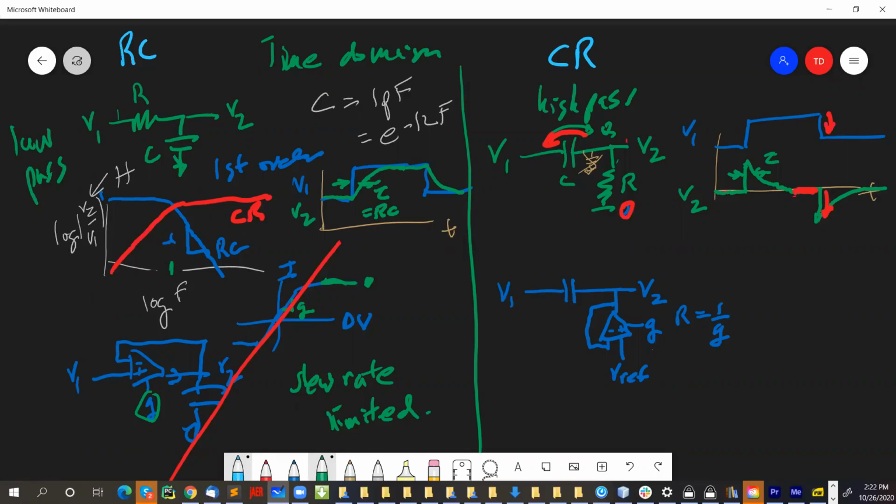A primary color. So this particular frequency here, which is called F3 dB, I'll tell you why that is later. F3 dB, it turns out that it's 1 over 2 pi tau. You divide the 1 over tau, which is a frequency in radians per second, by 2 pi to get hertz.